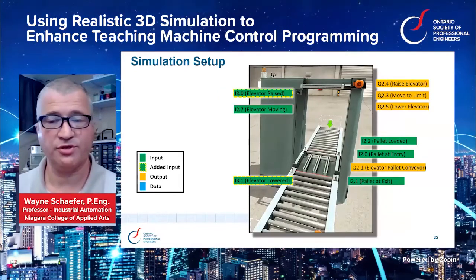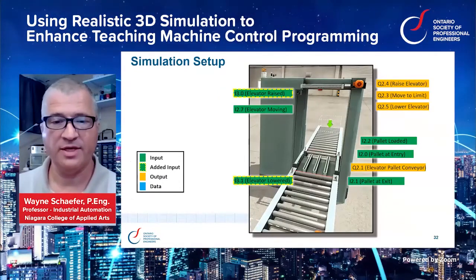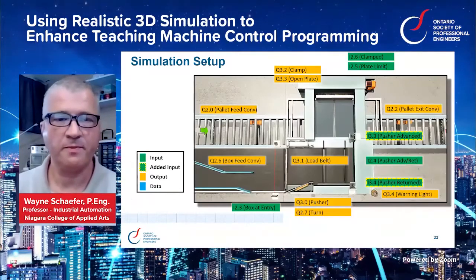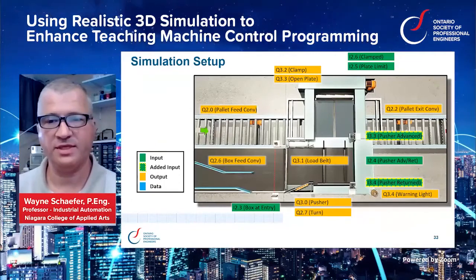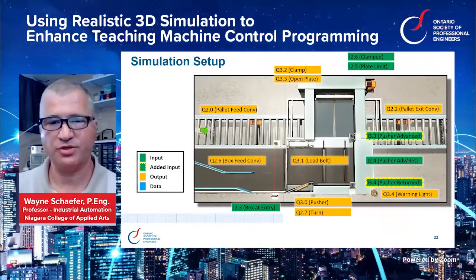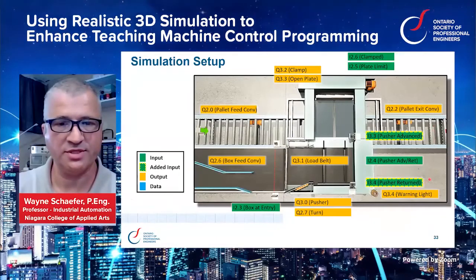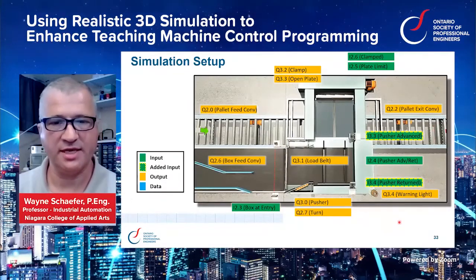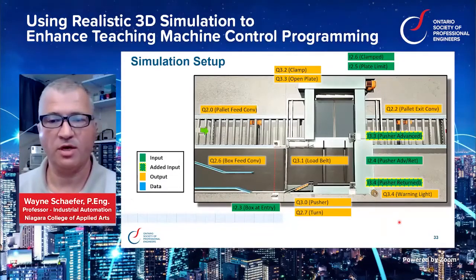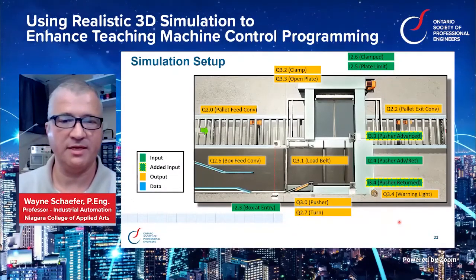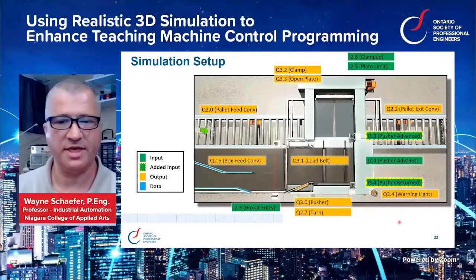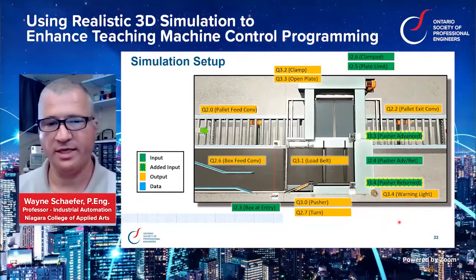As far as the outputs are concerned, there's a motor to raise and lower the conveyor, as well as one to move the pallets into the elevator via the chain conveyor. If we look at the top view of the elevator, we see that it's a box organizer. Along with the standard supplied inputs, I added pusher advance and pusher return proximity switches. Again, just a little addition to the standard scene. There's only one input for the model showing clamped advance and plate at limit. And this is where it allows me to demonstrate some different programming styles. So it's sufficient for what I need.